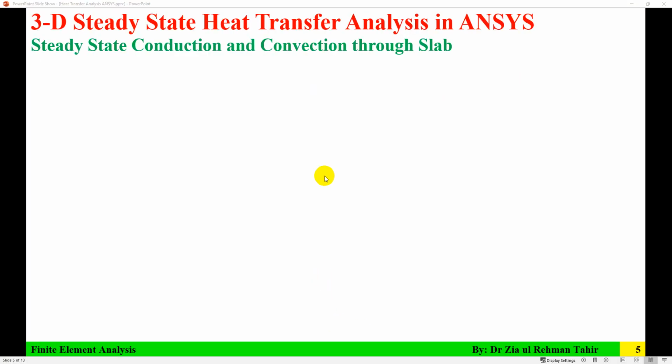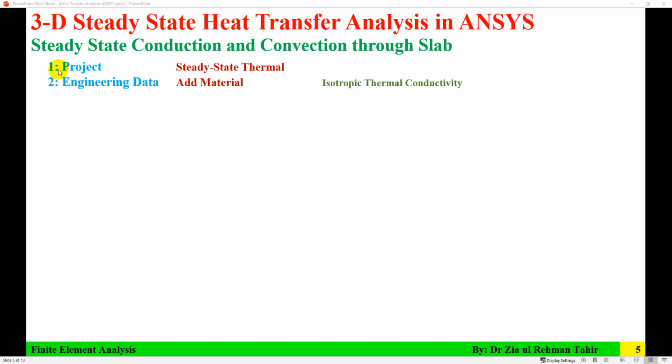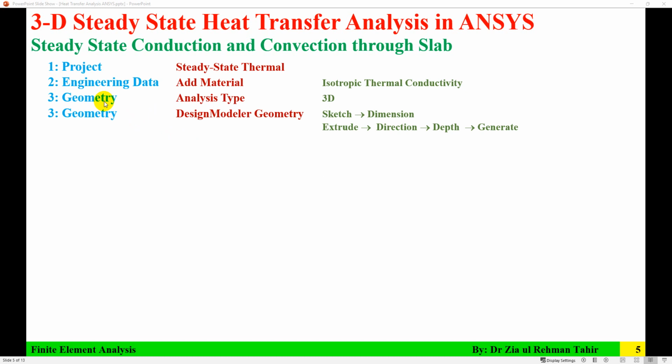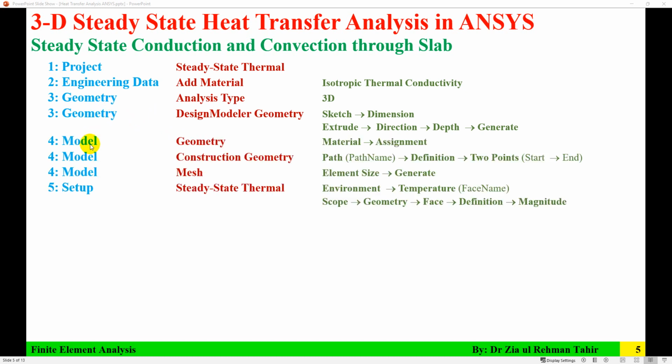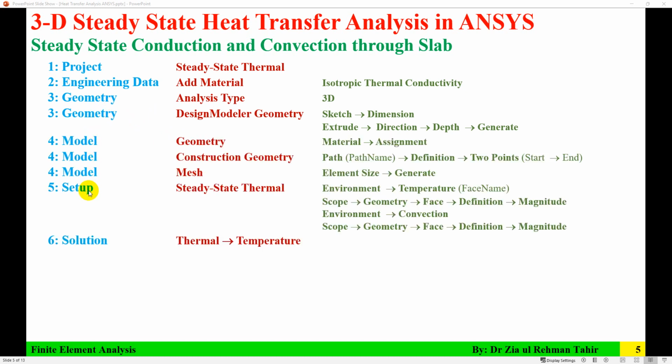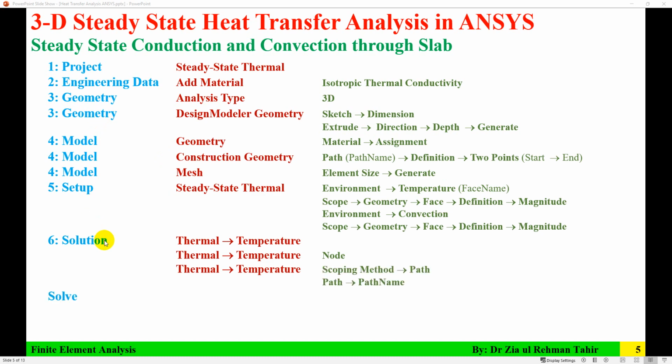So here are the steps to perform this analysis in ANSYS Workbench. The first one is project, then engineering data, then geometry, then model, then setup, then solution, and then results.